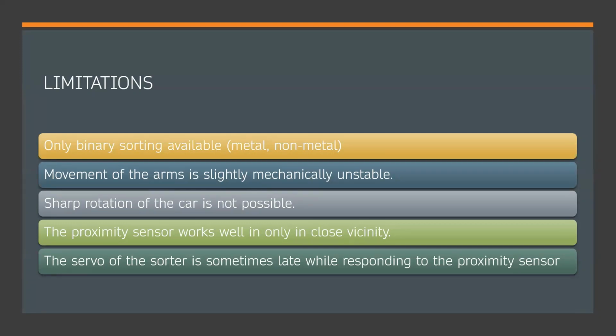While dealing with the instability of the arm, we tried to fix it by limiting the shoulder movement, but we could not quite solve it. At times, the hand was a bit shaky, which created problems while lifting the bucket. We could not make the vehicle move sharply, as that would necessitate high-cost mecanum wheels.